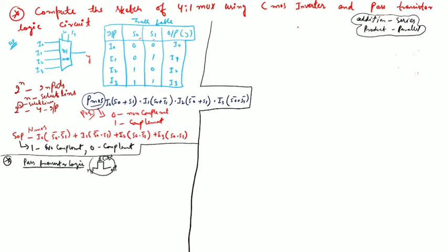According to this equation we will make the PMOS or pull-up circuit in the sketch of the CMOS inverter. And for NMOS we will follow this SOP equation, sum of products. First we will do the product of these select lines with multiplication of this input, and then for the next input, between the first and second input, we do the sum of the equations.